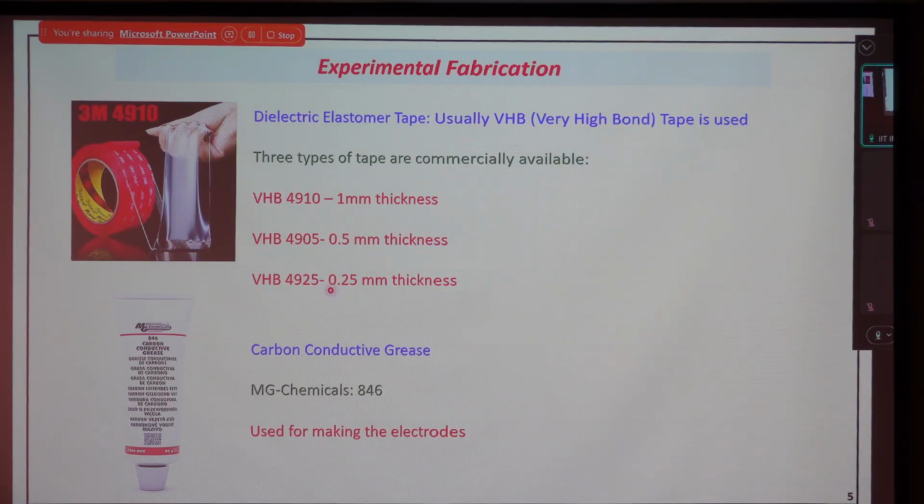So now you apply the voltage. If you have a pre-stretched membrane and an unpre-stretched membrane, for the unpre-stretched membrane you require a particular voltage, for example, for actuation of the membrane, but less voltage is required in the pre-stretched membrane to get the same actuation. Why, you understand? Is there any reason?